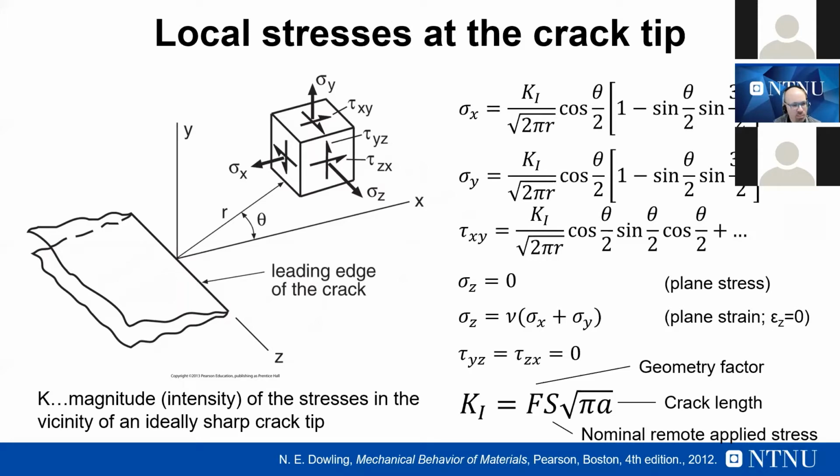This means that the plasticity has a small effect or does not affect at all the stress distribution close to the crack tip. And in fact, the equations of Irwin are based on this consideration and assumption. And so you have the equations reported in the slide that give you the sigma in Cartesian coordinates. These sigma in Cartesian coordinates are valid only under the linear elastic hypothesis.